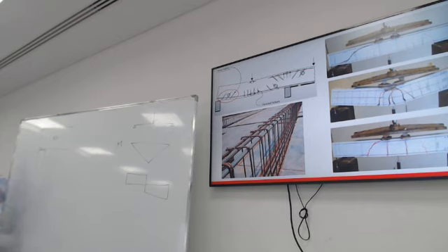But this element is embedded in the beam. It has nowhere to go. And therefore, there is an equal and opposite couple horizontal. Look at the vertical component of this shear and the horizontal component. It will result in a resultant of force going this way. The top two, horizontal force to the left, vertical force upward, the resultant is a force going this way.